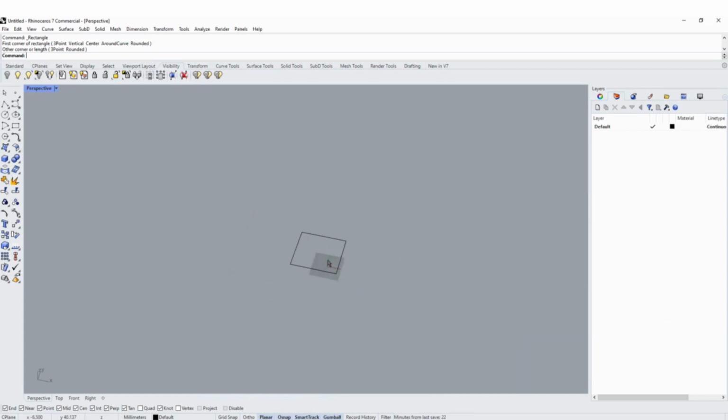So we have the zoom in, zoom out, pretty simple. You can also do it by right click and control. Then you have the orbit, that is just the right click, perfect. And then you have the pan, that is right click and shift.